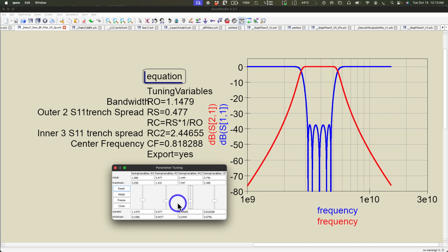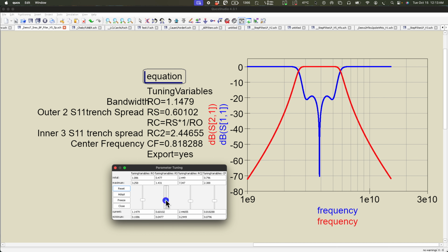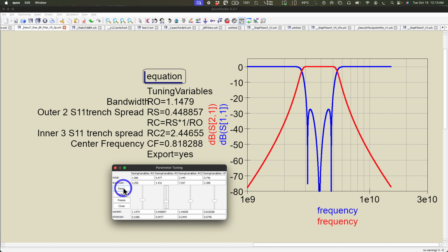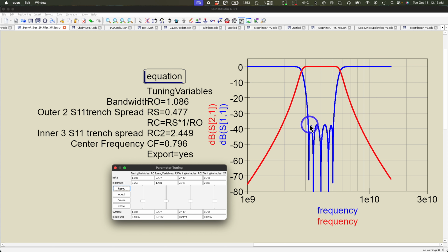Essentially, it's pairing components at opposite ends of the filter network, and that allows you to control a lot more than normal, in that you're otherwise forced to use a uniform distribution, such as if we reset this back to the beginning, a uniform distribution of the resonances. But in some cases, you might want to force that to a different combination than what the typical filter equations developed for the different styles of filters give you for a result. So this allows a lot more tuning in this methodology. So that's to give you a visual example.